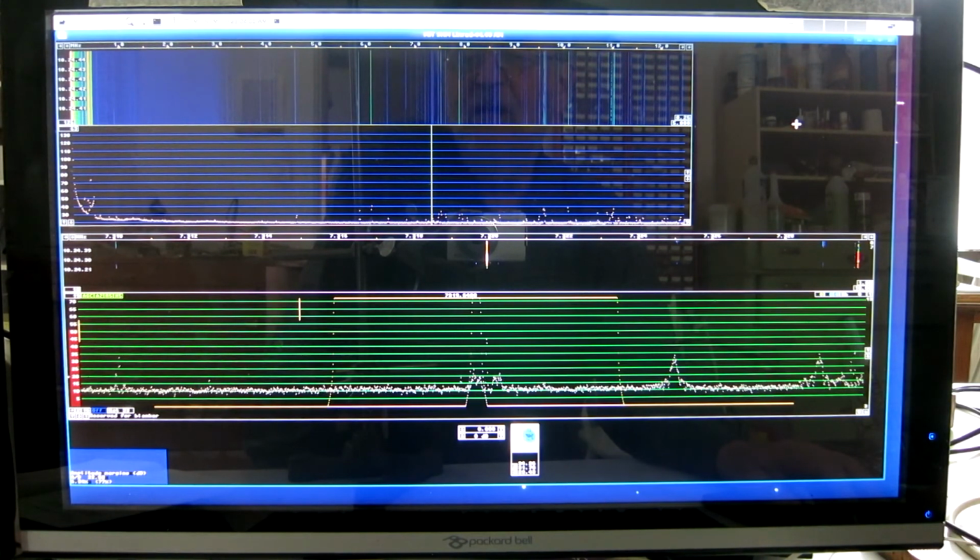Now, in Sweden, we don't have medium wave transmitters. In another country or in a location nearer to a transmitter, the performance of the card is needed if one wants the full bandwidth into it. And in many locations it may even be necessary to put a notch filter for the local medium wave transmitter.